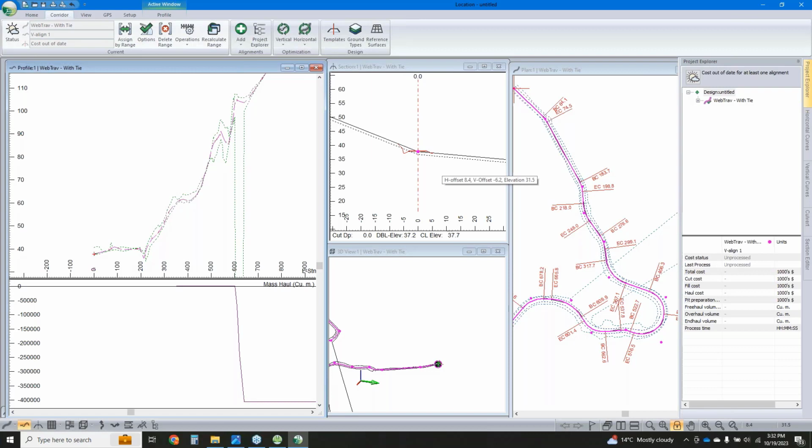So you have the P line as your preliminary alignment, but then as you work through the design process, inevitably the two lines aren't perfectly equal. And so if you have little offsets here and there, the lengths are different. So your P line station and your L line station are different there as well. Yeah, and that might be more apparent here as we step through these next few steps.